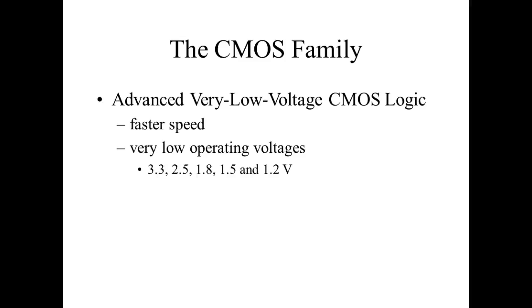But what they've done now, if you're dealing with the motherboards, is everything's dropping down to these voltages right here. 3.3, your processor's using 3.3. Now the microprocessor usually has about 2 or 3 voltages that it uses. It uses 5 volts to drive the buses. It uses 3.3 to drive memory, and it uses lower voltages to run inside.